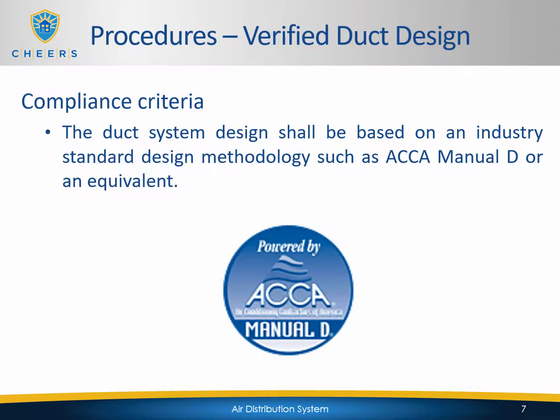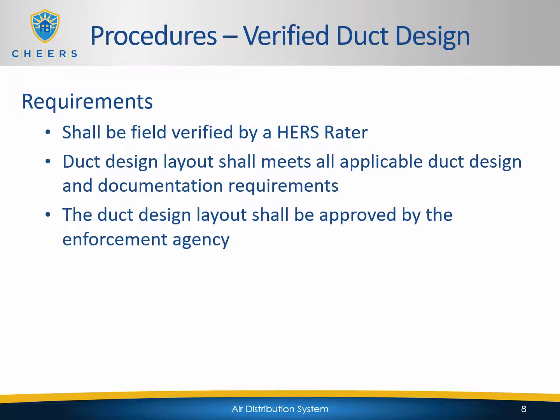So for compliance criteria, the duct system design shall be based on an industry standard design methodology such as ACCA Manual D or equivalent. The requirements are that it shall be visually verified by a HERS rater. The duct design layout shall meet all applicable duct design and documentation requirements, and the duct design layout shall be approved by the enforcement agency, meaning that it was submitted and approved by the actual building department.